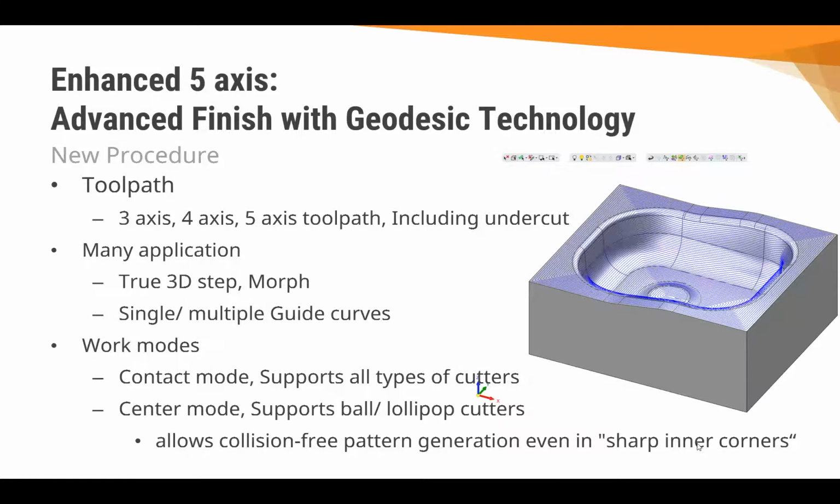It has different working modes with regards to contact mode, which supports all types of cutters, or center mode for supporting ball and lollipop cutters. It also allows the collision-free pattern generation with these tools for sharp inner corners.